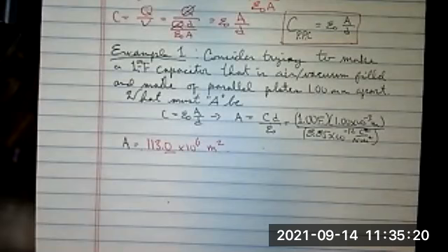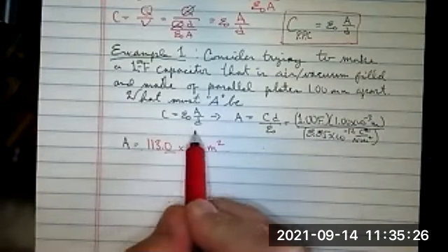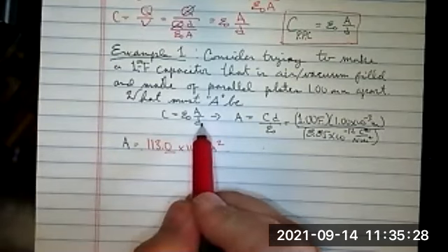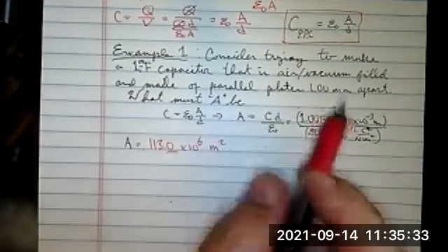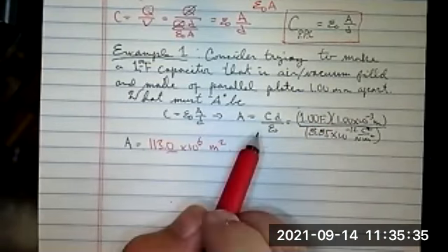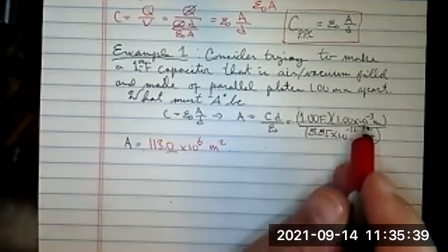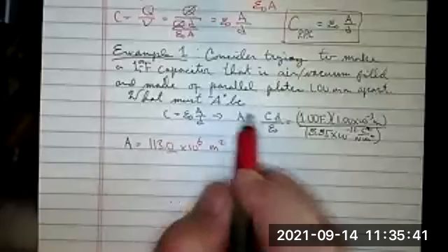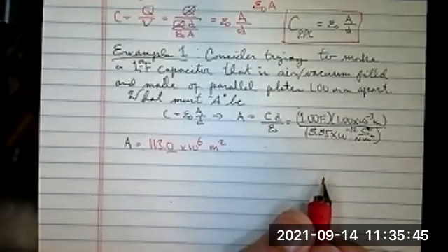So yeah, a 1 farad capacitor is something that's not that easy to make. Now notice the capacitance goes up the smaller the d is. So using 10 to the negative third was actually helpful, right? But using 10 to the negative third also meant the area had to be even larger. So that's where the downside of that is.